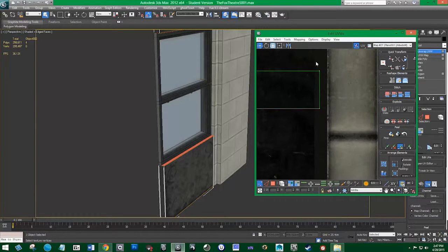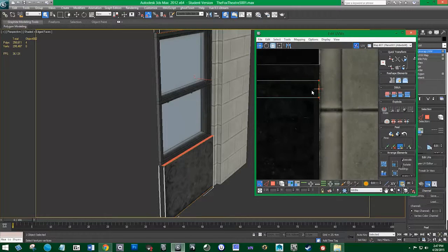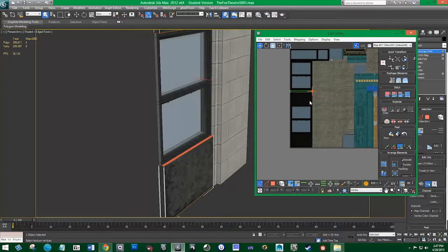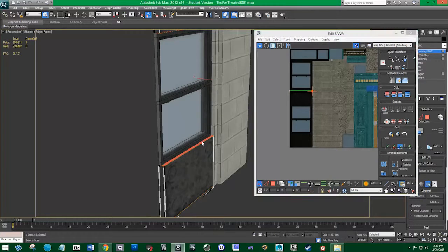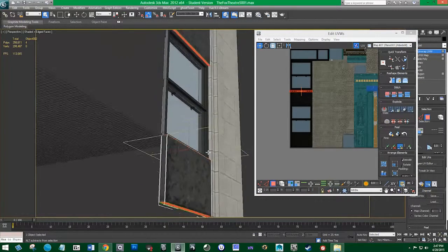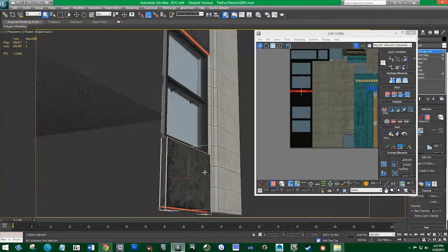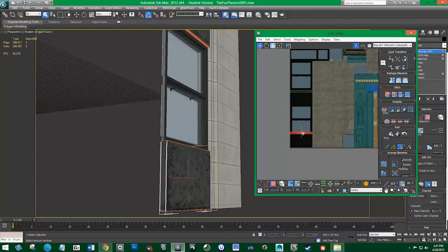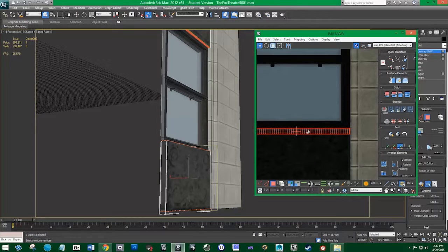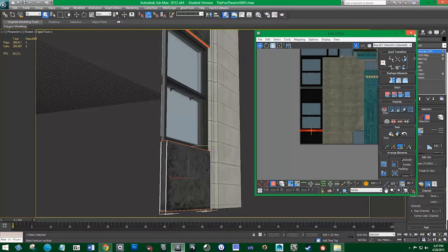So let's go to our polygon tool, click on this one, and then the one beneath it. Oops. Make sure you hold Control and not Shift, otherwise you'll select everything between. And I think I just moved that one. So hit Q, and Q will not move it because it's not going to move selection.